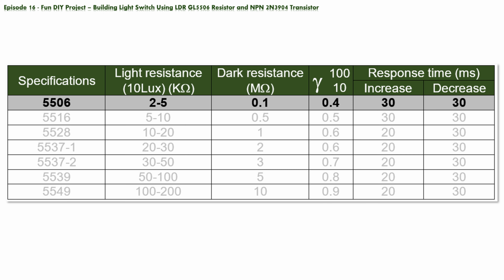Not very important for us, so we will not dwell over this parameter too much. And at the end, there is response time given in milliseconds. This parameter tells us that it takes 30 milliseconds for LDR to establish its resistance after change in light level. So, we have to keep in mind that change in resistance is not immediate.